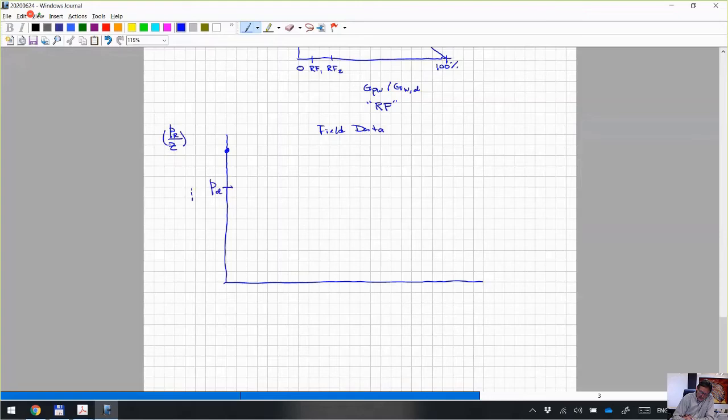Down below here, we're using Z equal to the two-phase Z factor, and above here, we're using the actual gas Z factor. So we start getting production data, and let's say it's an ideal reservoir. It's a straight line material balance. Let's just say that we start getting these data. High permeability, so you expect a single reservoir flow unit. You got some scatter, make it look real.